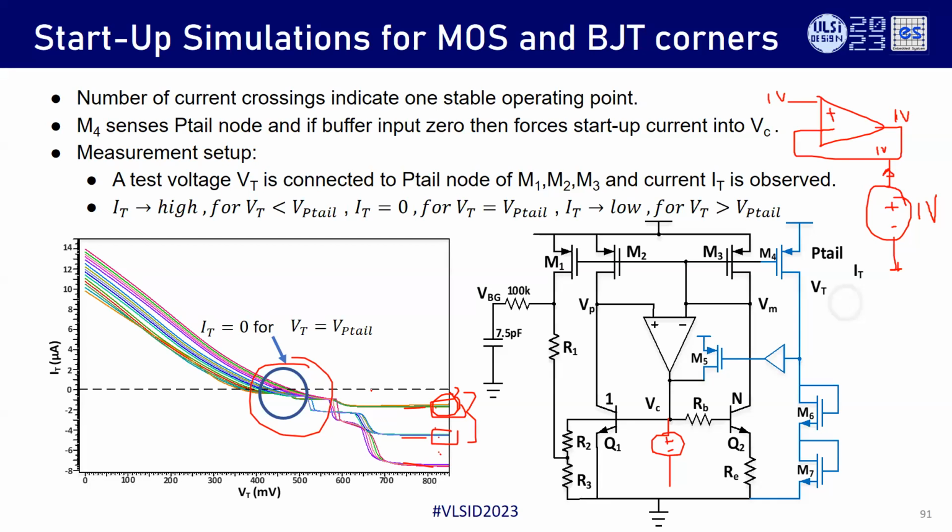But why this test is important is there could be some hidden point of, let's say, 0.3 volts, though our DC sweep is different, DC operating point is different. Sometimes Cadence, or any circuit simulator, magically catches this 1 volt. There could be several operating points. It could catch this 1 volt and live there. But we need to experiment with all voltages and see whether it will travel through 0 to VDD, and see if there are any stop points rather than directly landing on the actual point.